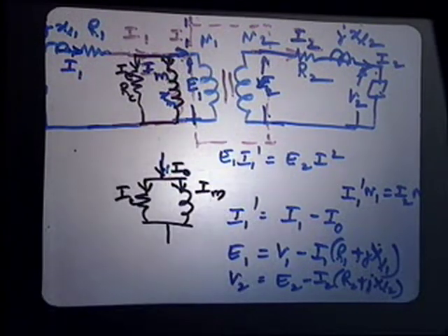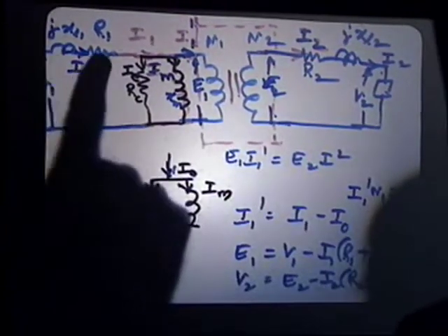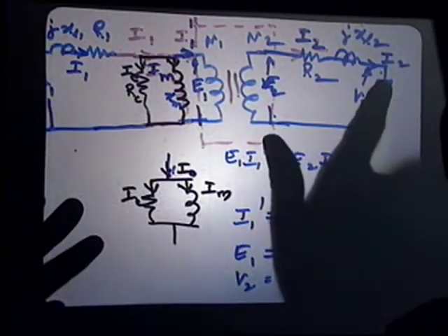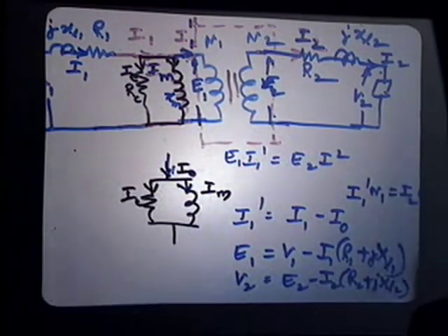Why do we take less voltage when we do this short circuit? When you do a short circuit, you have to operate at rated current. If you increase the voltage, the current will increase. So you want to operate at rated current, and you don't want to operate beyond rated current.